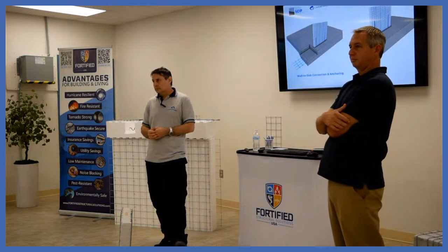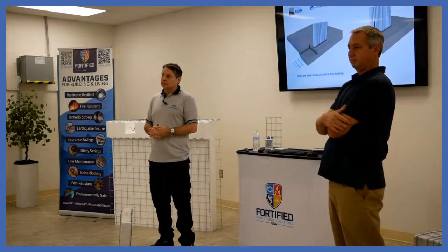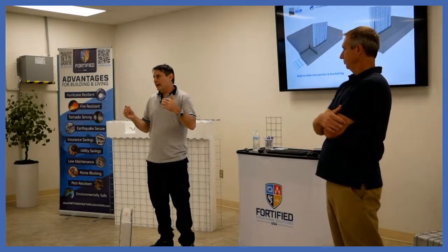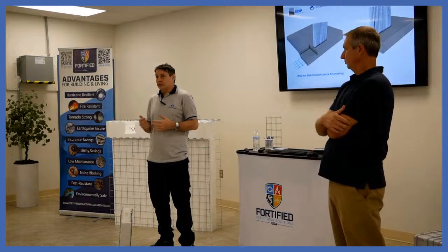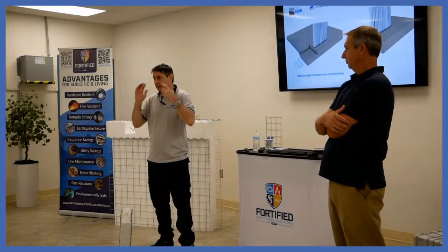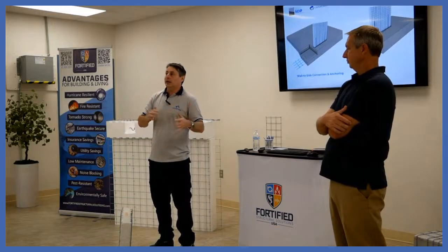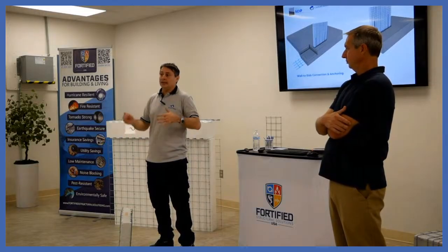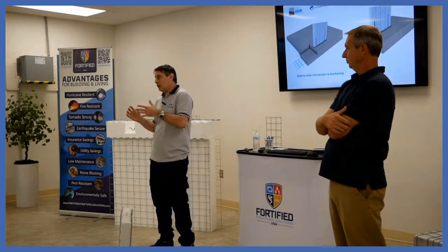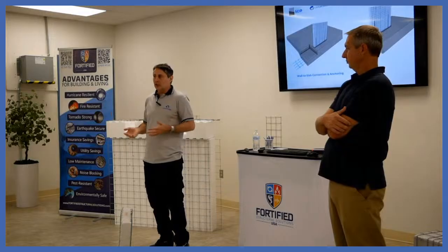The loading capacity of the wall panel is super high. But you have to keep in mind that it is just for dead and live loads. Then you have wind loads and other loads. And also, of course, imagine that you have openings, so you have to see how they match with that. It's not that simple.